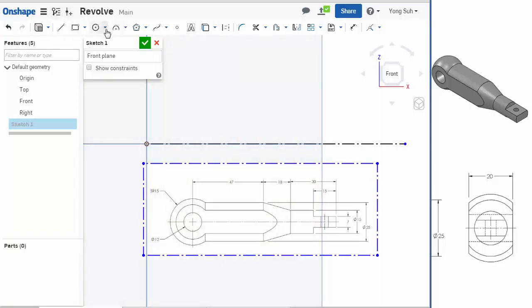So I'll start drawing an arc. Maybe center point arc would be good. So starting from the center, draw a line somewhere like here. It doesn't have to be exact. Just draw the shape of the outer profile. And here it goes down, but the thing is there's a step at the end, so I'll just create the whole thing as a cylindrical thing and then make the cutout later.